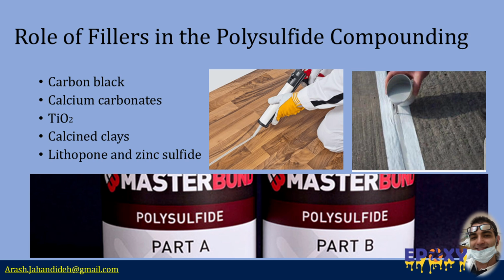In insulating glass sealants, a small amount of titanium dioxide is added to whiten the base formulation, while a touch of carbon black is typically included in the catalyst side to provide color balance. Calcined clays are consistently incorporated in building sealants. Their purpose is to help neutralize the alkalinity introduced by calcium carbonate fillers, thus enhancing long-term stability and compatibility within the formulations.